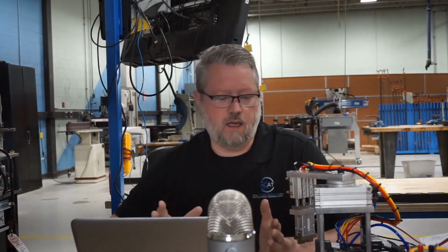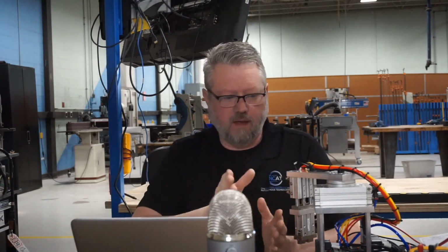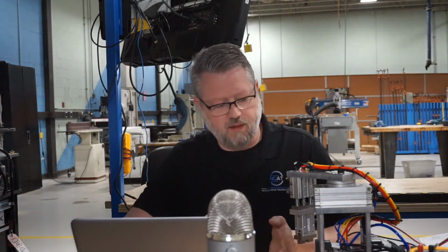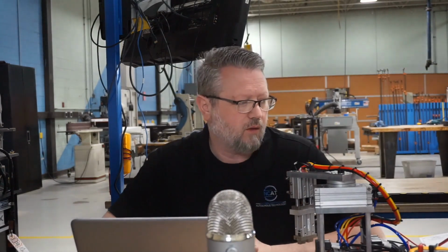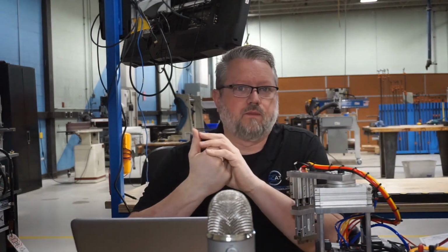Likewise, on the output side, when we turned on and off a valve, that valve had two states, on and off, 0 and 1. When the valve output was off, it did not move, and when it's on, it would shift and cause the air cylinder to move up and down, or it would turn on the buzzer or the horn or whatever it was. So those are two states, on and off. The analog inputs, by contrast, have many different states.